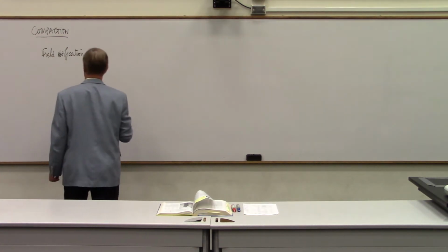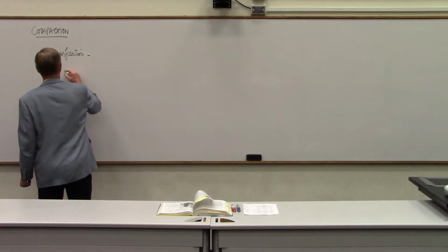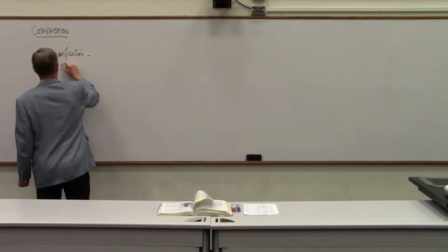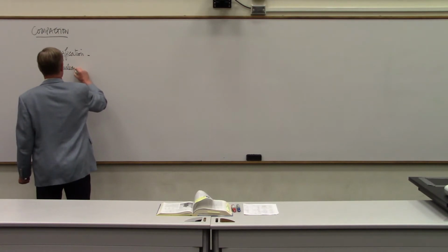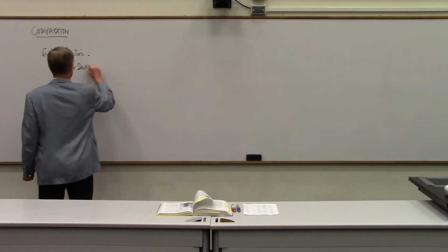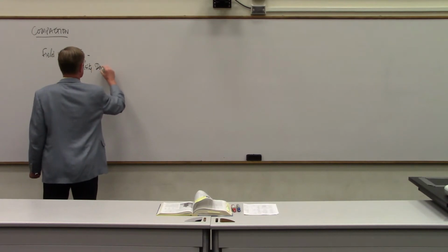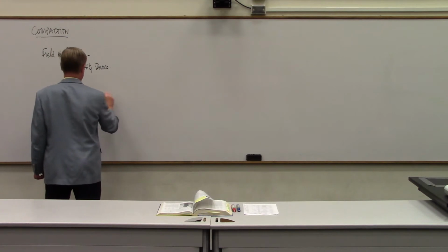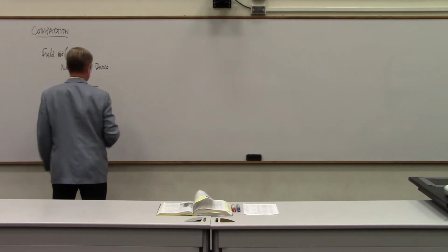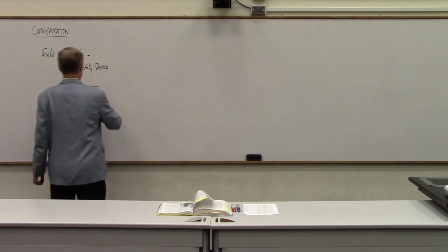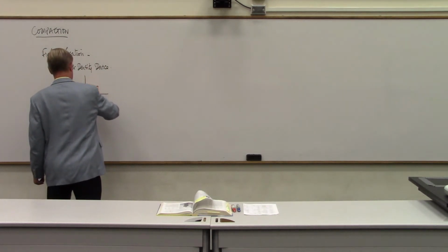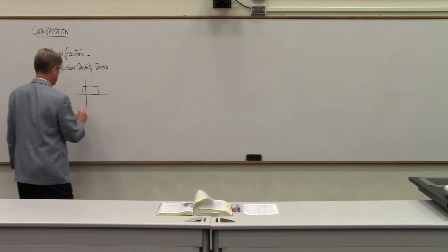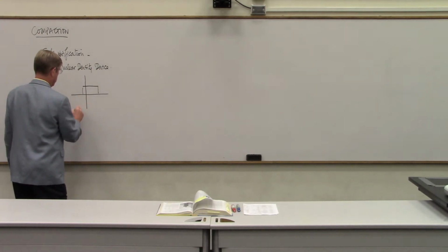So how do we do that? Well, most commonly we do that with a tool called the nuclear density device. And this device is about the size of a box, and you push into the material a rod that can go up to about 15 centimeters approximately.